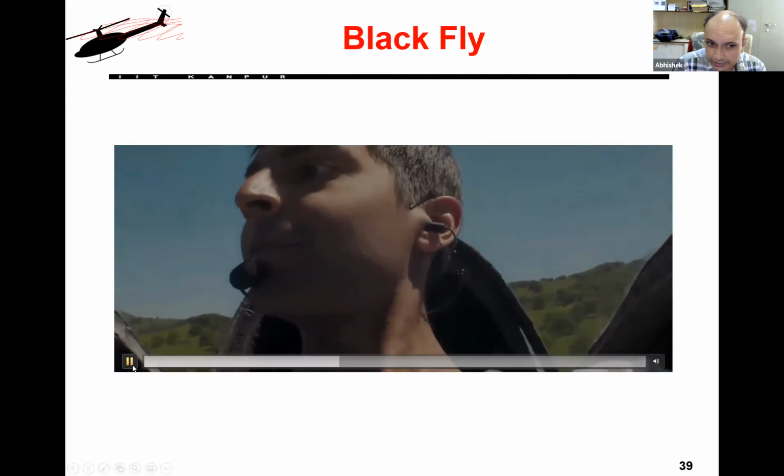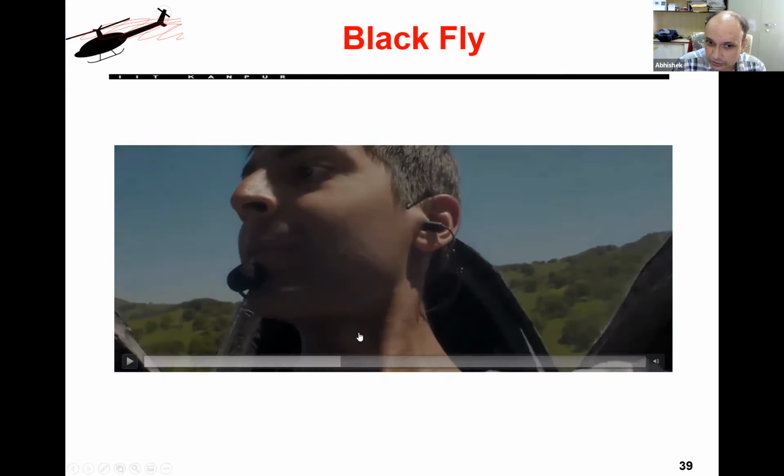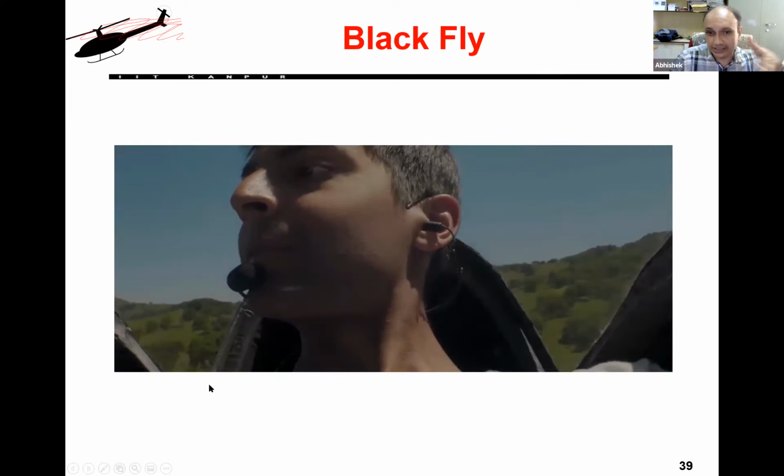But it's not actually a tilt rotor or a tilt wing. This actually is close to being a tail sitter, but almost half tail sitter, in the sense that the vehicle has a body whose bottom is made like a boat. So it can land on water, and it can do a rocking takeoff. It will sort of rock on its back and take off.